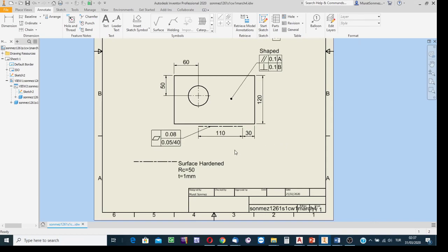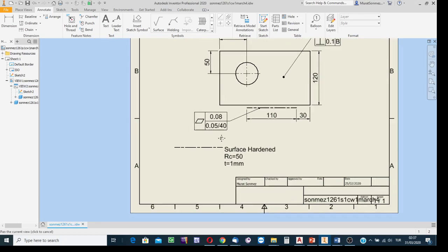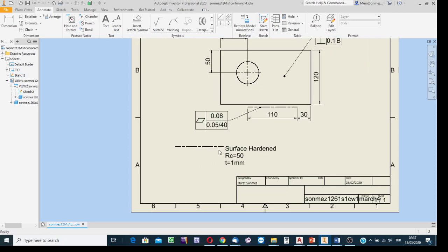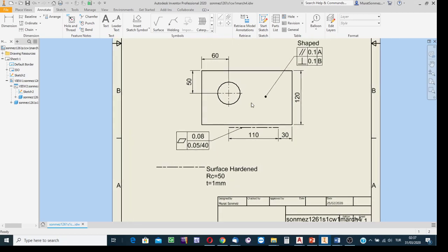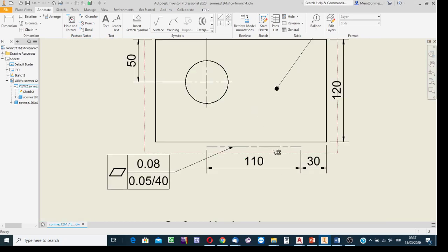Yes, a chain line is a thick interrupted line. It uses long and short dashes. It is a thick line. It is long dash, short dash, such a format. It looks like a symmetry axis, but it is a thick line. If the thickness of the line is thin, it means it is a symmetry axis, but if the thickness is thick, not 0.2 but 0.5 for instance, it's a thick line. If it is in the thickness of visible outlines, then this means it is a chain line.